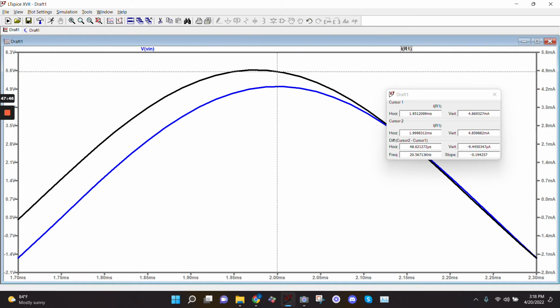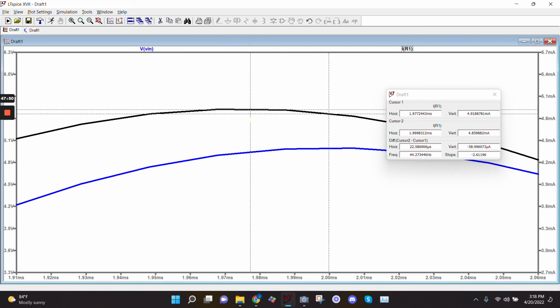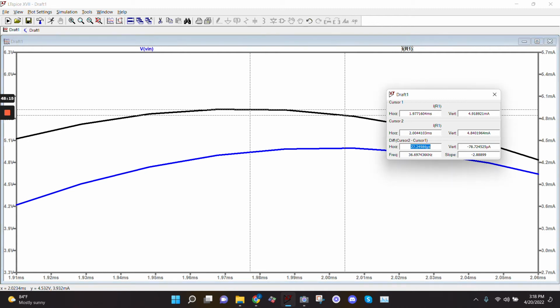Oh yeah. Okay, so here. I move this. You can get as close as you want to these peaks, and then you just put them at the peak. So I'm assuming that that's the first peak right there. I'm just putting that there. And then, like I said, I can't put another trace on the blue one. They're both on the black one. So I'm just going to try and move it horizontally to where I think the peak is. I might say it's right here. And then it gives me, okay, I calculated 25 microseconds and this gives 27. It's close enough.